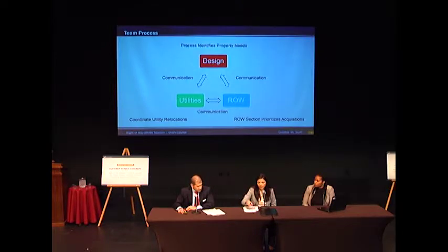In regards to design, we have ongoing communication to assist in identifying who the stakeholders are, who are the utilities out within the project limits. And we also brainstorm ways to avoid, minimize the utility conflicts and to identify the conflicts early on. As it was previously mentioned, in San Antonio, one of the things we're doing is our 30% PS&E design phase or submittal is actually more of a 60% design submittal. We're including underground improvements, we're including drainage, retaining walls, we're including a lot of things earlier, so we are able to identify conflicts early on.